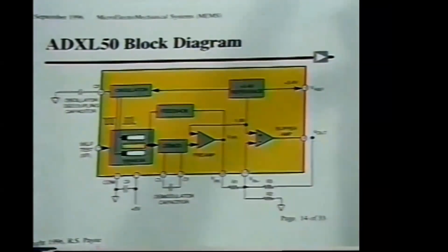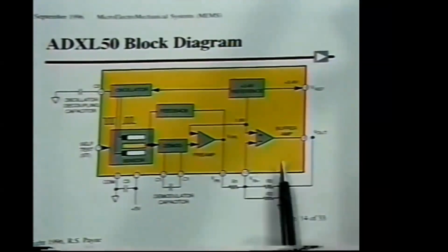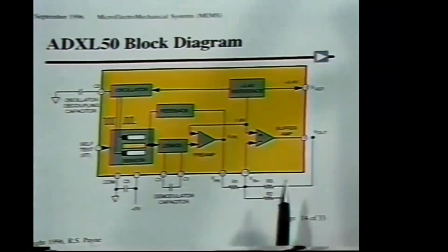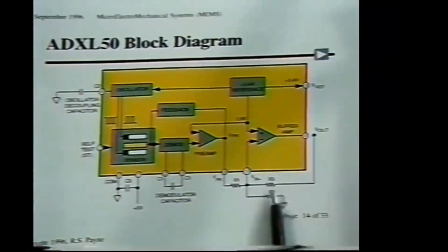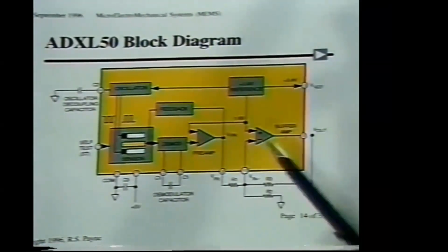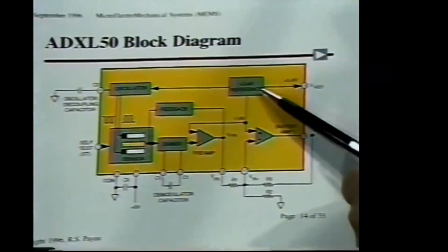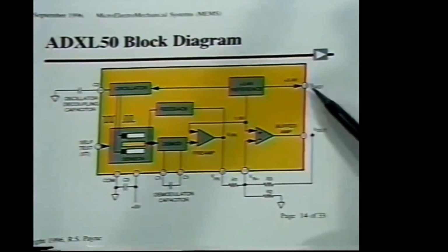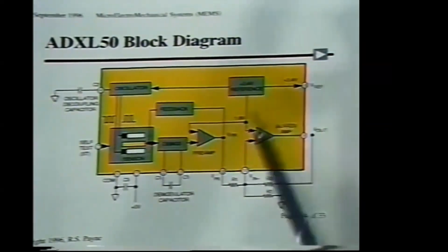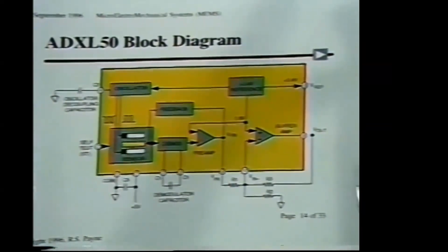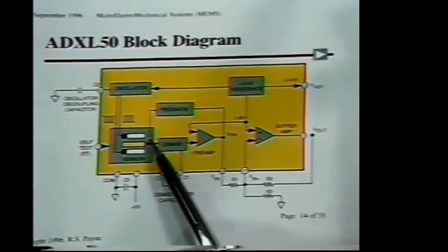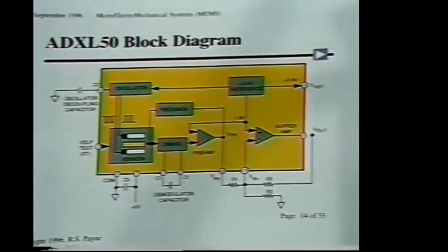That output is then fed to a final stage amplifier. That's the case because in the early days, we had 3 partners, and each of them wanted a slightly different range. So we reached an agreement where they could set the final gain. We would provide a calibrated signal, and they could amplify the output or filter it at this point as they saw fit. It also came with a standard reference building block such that the output was an absolute value of acceleration. Shown here is a block called feedback. In the first system, which I'll describe a little more fully, there's actually a closed force rebalance loop that essentially keeps the center member very close to its null point.